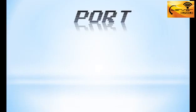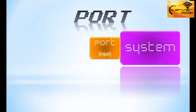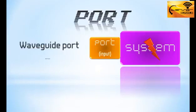First of all, an input port must be defined. Roughly speaking, a port is a place where the power is propagated into the system from outside. In this case, the antenna is the system, and CST Microwave Studio supports two types of ports, waveguide port and discrete port. I'm going to use waveguide port with this antenna, and this kind of port simulates an infinitely long waveguide connected to the system.